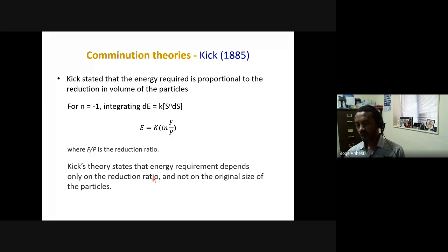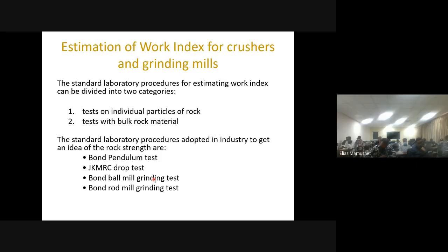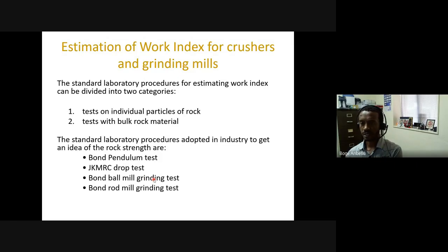And therefore, if you wanted to use a model that may handle a wide range of particles, then the Bond equation is by far one of the most dominant ones. And there are standard procedures which are developed to determine the Bond work index for rock particles. And in your lab practical, I was hoping maybe you can actually calculate that for a given sample. So for my students here, we actually take a sample in the lab and use Bond's method to work out grindability.